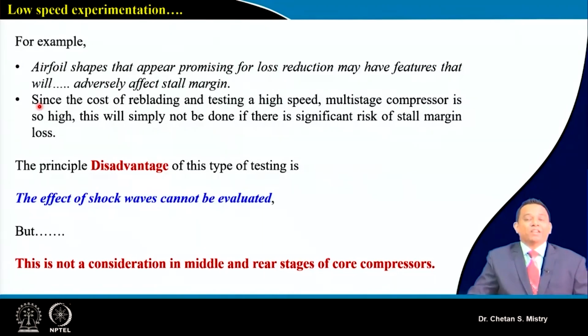So the method we are discussing, in terms of aerodynamic similarity or transformation of experimental facility from high speed to low speed, can be safely used when we are discussing the design of HP compressors.